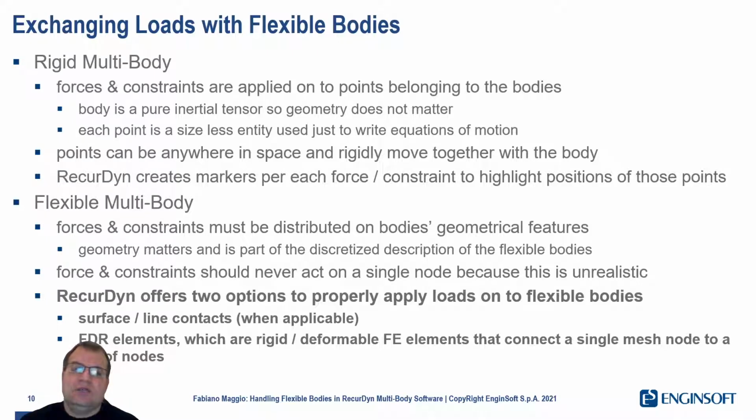Second, if you want to apply loads to a flexible body, you have to distribute that load over a certain extent of surface, because this is what happens in real life. And so the shape of the geometry, the curvature, the extension, they all matter. And it's important to select these areas before making the body flexible.